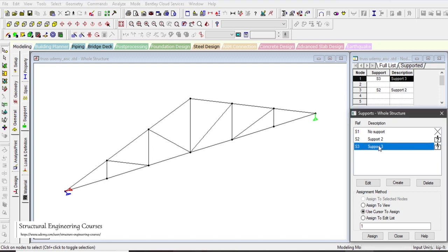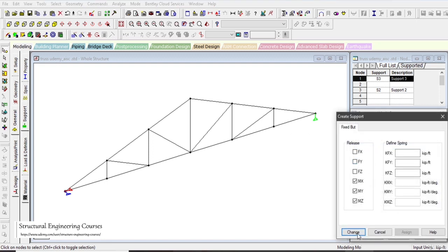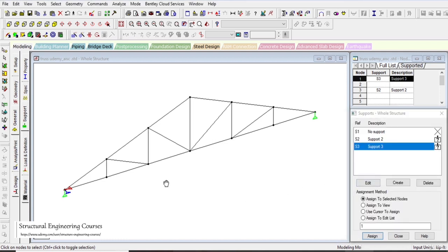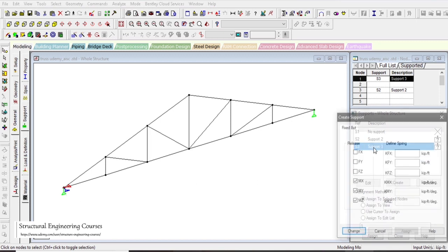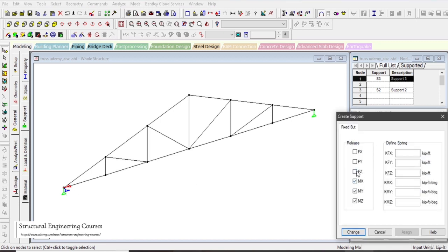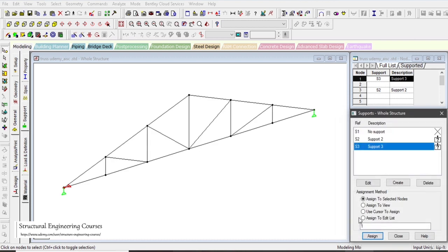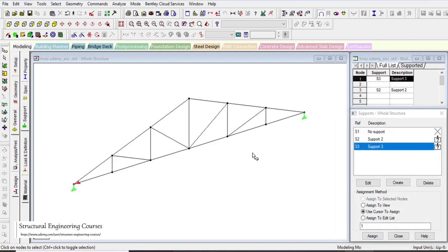In addition, what we can do is that we can also make it indeterminate. So if required, we can make it determinate in the later stages, but just to make it a practical case here, it cannot take these out of plane forces here. So we can release the Fz here. Yeah, now this is a correct practice that we are following here.